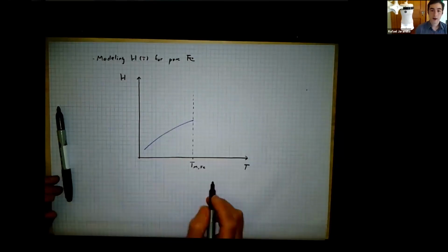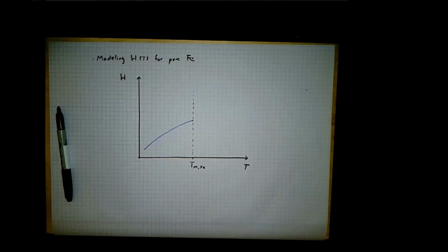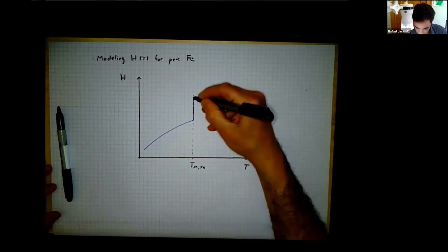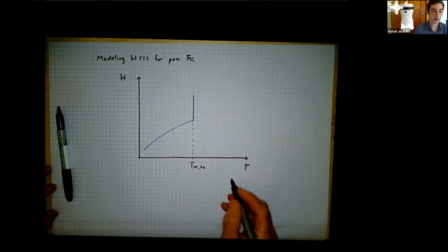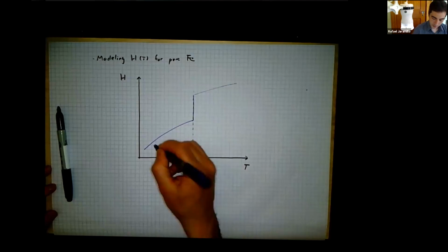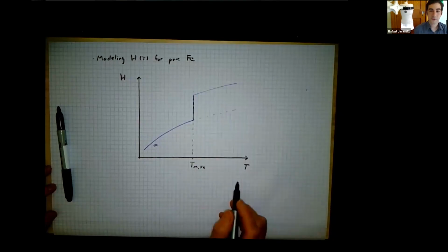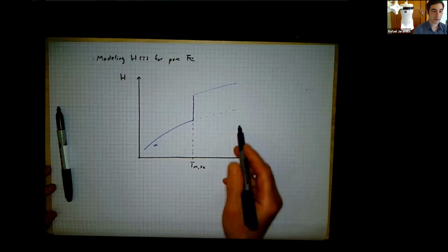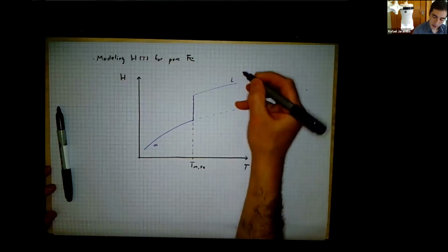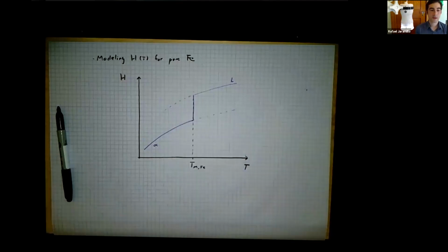Okay. What happens at the melting point, at the enthalpy? How should this curve look? It should jump upwards. That's right. There's an enthalpy of melting, right? A specific heat of melting. And then it continues on its way. So this here is the alpha phase. And we know that in principle, I can imagine the enthalpy of the alpha phase being a function that continues. In practice, this might be increasingly hard to measure or to calculate. And here's the liquid phase. And I can, of course, imagine this being a function that continues, but becomes increasingly inaccessible.